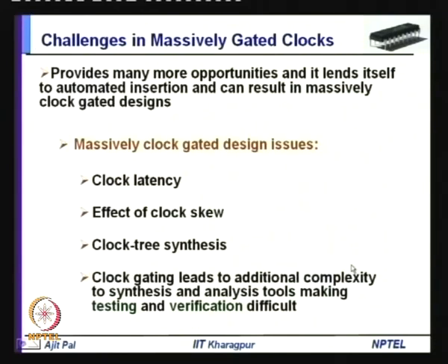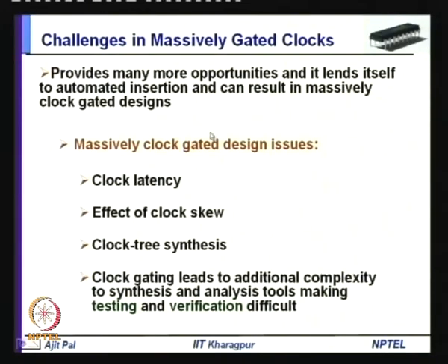Okay. Now, today there is opportunity to implement clock gating in a massive way, and automated tools and techniques are available by which this can be done. So, it provides many more opportunities and lends itself to automated insertion of clock gating hardware, and can result in massively clock gated designs. So, it is a reality in the present day VLSI circuit design.